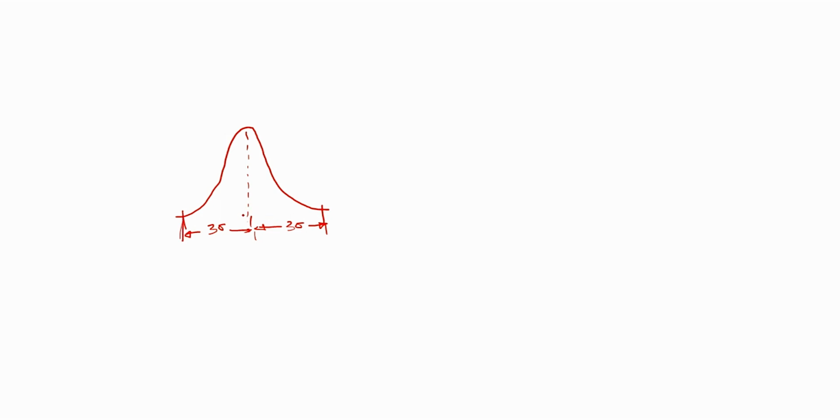So this is the case where we have a normal distribution curve like this. Let's say process A or machine A has a normal distribution curve like this. It has a spread of this much, and I am trying to produce a part with tolerance on this machine, and then I get a tolerance something like this. This is the lower limit of tolerance, this is the upper limit of tolerance.